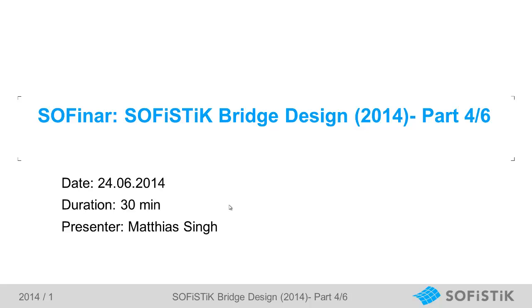My name is Matthias Singh, and today we're defining the traffic load for our frame bridge, and for that we are using the live load analysis task, which you can find in our library task in SSD. In today's SOFinar the focus will be just on the Eurocode, but there are also other design codes available like AASHTO or British Standard. We are looking for the envelope of the minimum and maximum forces and moments of the traffic load. That means the search for the most unfavorable load position for every single element.